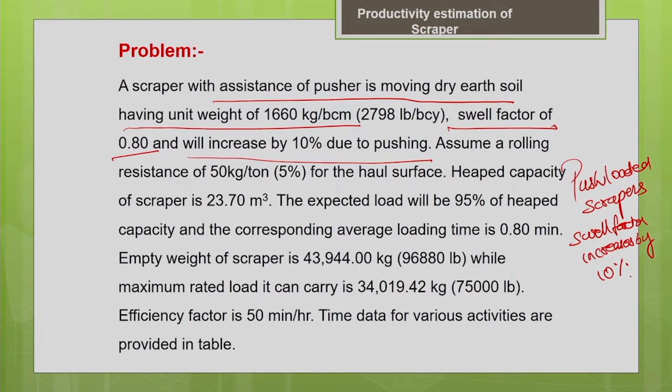When the pusher is pushing the scraper, it offers additional pressure to push more material into the bowl. Because of that additional pressure, more and more material gets compacted inside the scraper bowl. Due to the compaction of the material inside the bowl, the unit weight of the material inside the bowl will increase. That results in an increase of your swell factor.